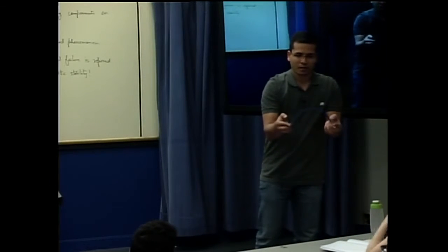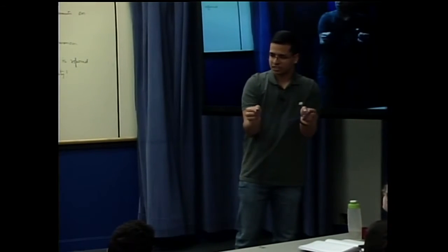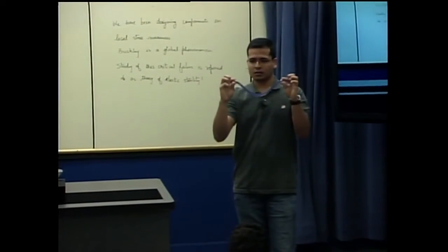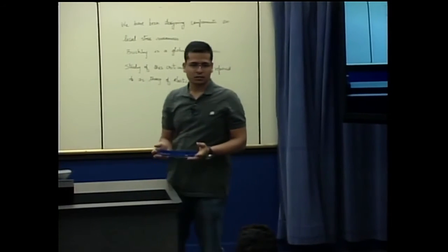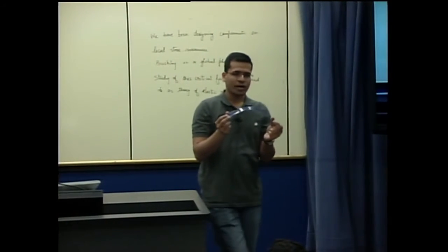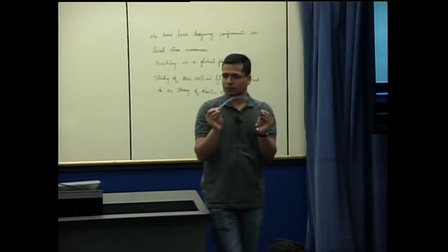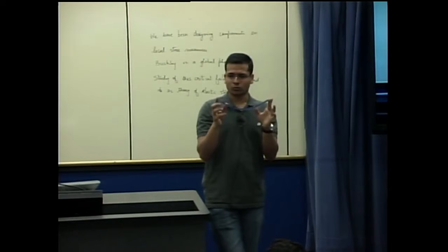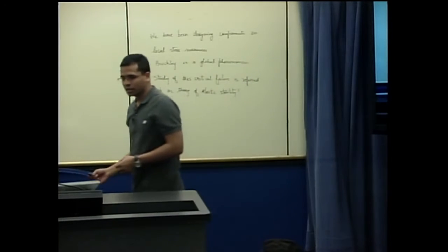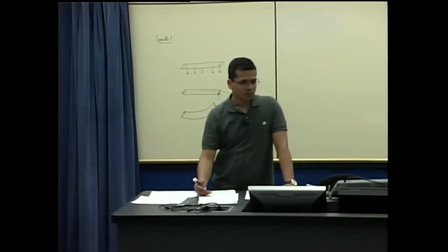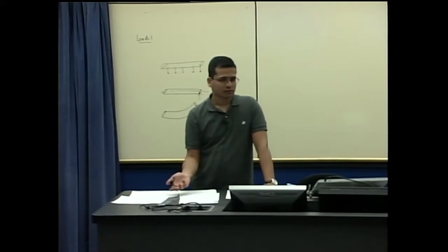So you see that after some time, there is another position which is stable. If there is a vertical load applied on this object such that you have another path which is stable, that's called snap through buckling. So what this means is that based on the loads in the system, you have another equilibrium path which is far from this equilibrium position, but it's stable. If you keep applying that load again, it's not going to move, right? So this is another type of buckling. In this course, we'll study all three types: the post-buckling path is stable, the post-buckling path is unstable, or snap-through buckling. Okay.